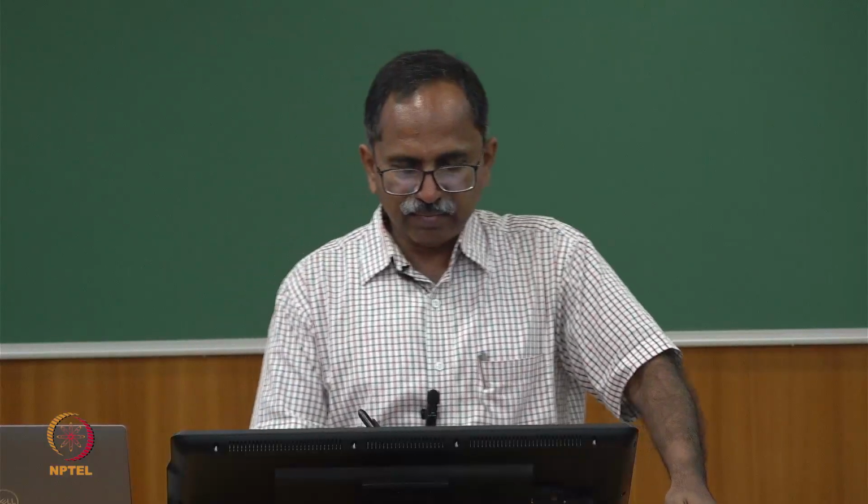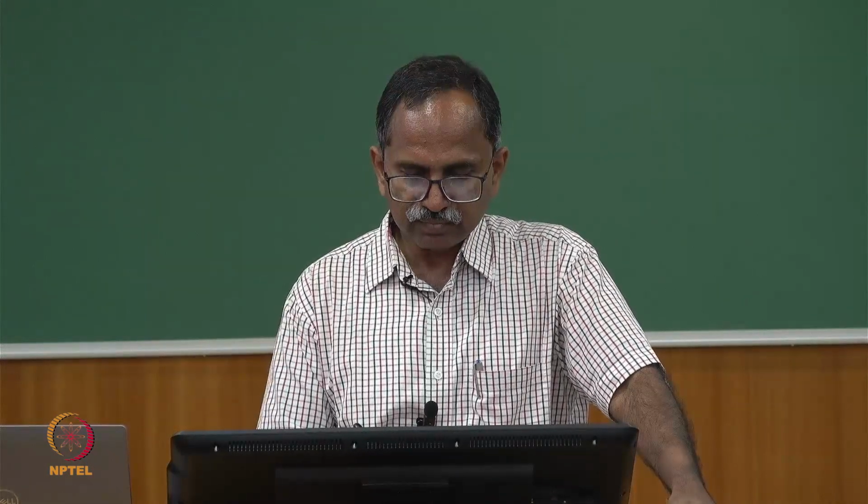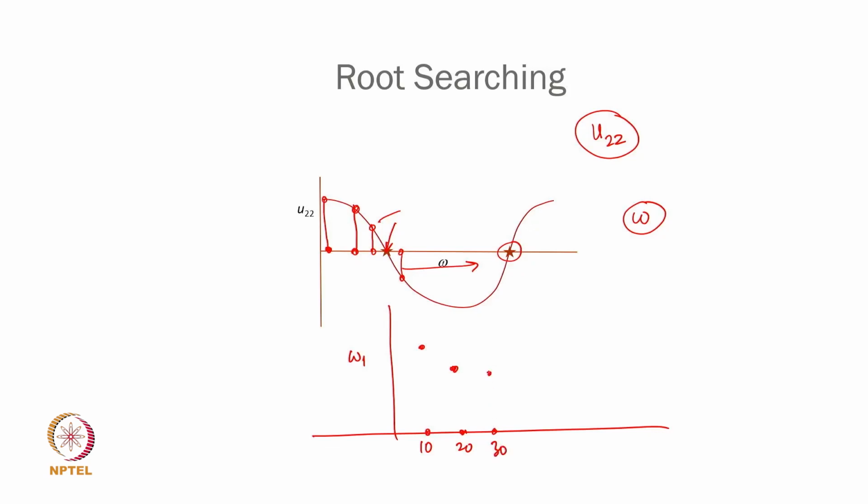Now what can be done by you is that same system, if you discretize into, let's say, 10 segments, find out what omega 1 is, maybe you will get this value. Then instead of 10 segments, that entire gearbox you discretize into 20 segments, reevaluate omega 1, maybe you will get this value. Discretize into 25, 30 elements, you will find that with a larger number of segments, this omega 1 will stabilize and approach a constant value.